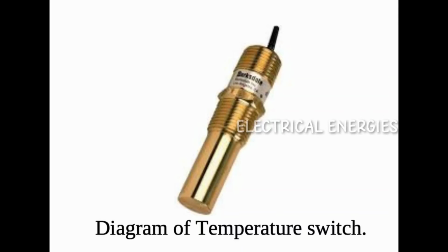Number 9. Temperature switch. Think of the bimetallic strip, an inexpensive temperature sensing mechanism. It comprises two metals joined in back-to-back fashion to form a thin strip. Each of the two metals has a different thermal expansion rate. When the strip is either heated or cooled, the differing thermal expansion rates cause the metal strip to bend. This bending effect may then be employed to activate a switch mechanism.